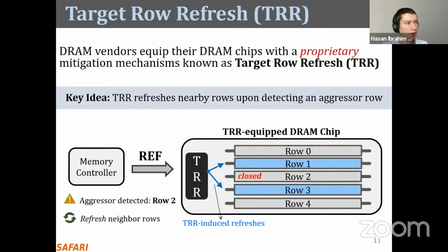Basically, the TRR mechanism uses these refresh operations to perform the extra refreshes in a way hidden from the memory controller. The memory controller is not able to tell whether a neighbor row refresh happened or not, because the additional refreshes are squeezed in within the time interval normally allocated for regular refreshes.